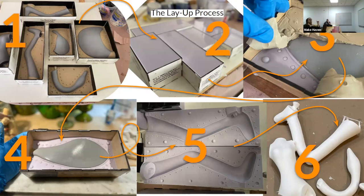And so the way that you do this is by putting your piece up to the exact halfway mark, the parting line, in a mold making clay, and then you fill and you use impressions to make these little nubbly bits, which are the keys, so that it registers later. But then you backfill it with rubber.